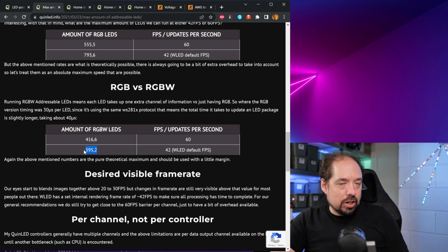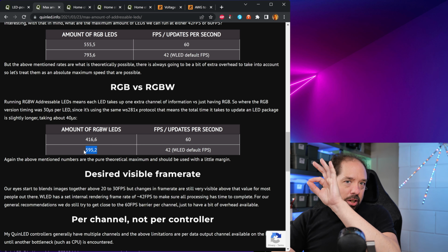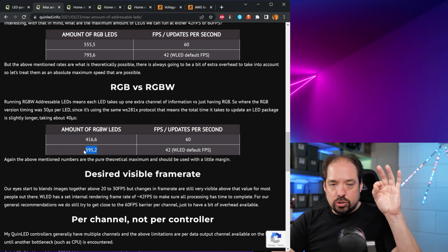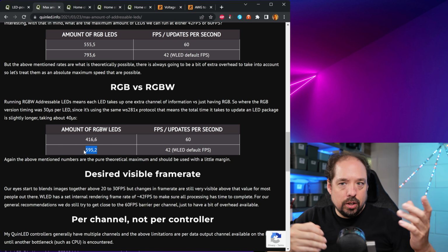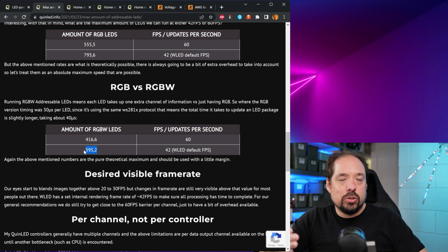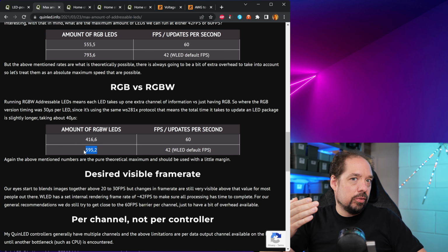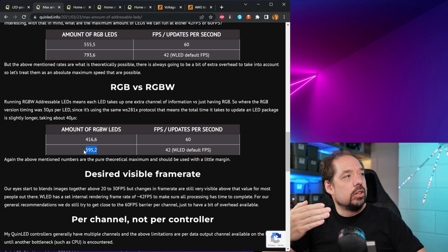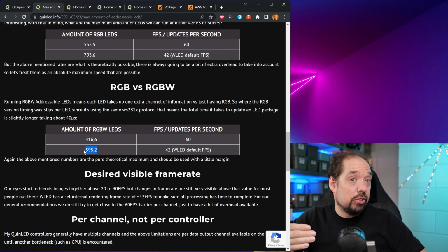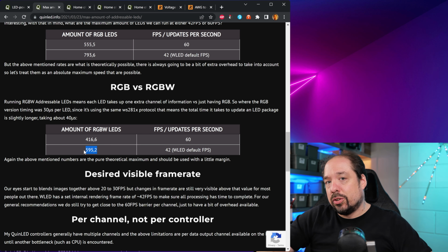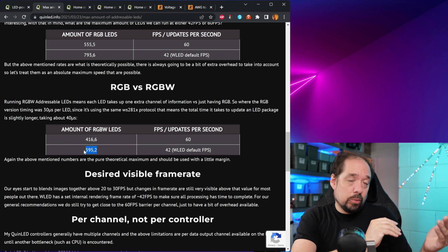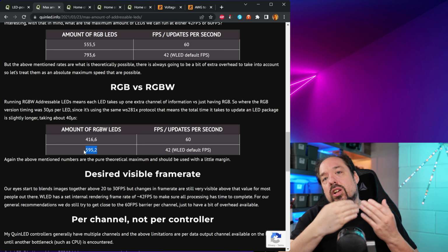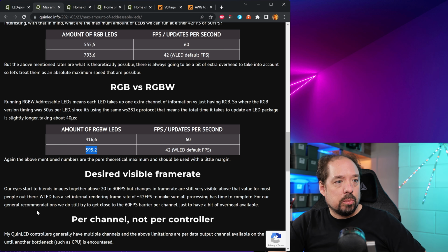It's not that it's not going to work, but the animations will just have less points to go to, basically, so it'll be a little bit choppier. But then again, if you move to 12 volt WS2814, TM1814 or SK6812, or 24 volt variants of those, while the amount of addressable zones drops quickly with the per 3 and per 6, then it's again much less of a problem.